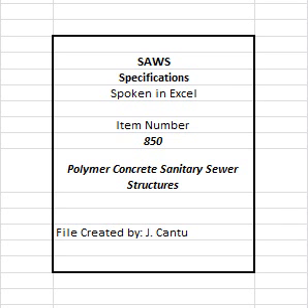9. Minimum clearance between wall penetrations and joints shall be per manufacturer's design. 10. Construct invert channels to provide smooth flow transition with minimal disruption of flow at pipe manhole connections. 11. Invert slope through structure as indicated on drawings. 12. All precast base sections to be cast monolithically. 13. Polymer bench and channel are to be constructed with all polymer concrete material. 14. Extended ballast slab requirements for buoyancy concerns can be addressed with cementitious concrete material. 15. Structures shall have engineered and rated lifting devices that shall not penetrate through the wall.